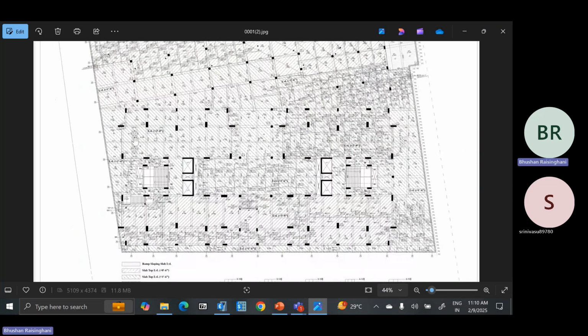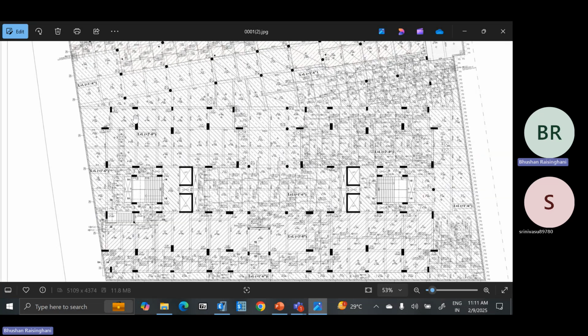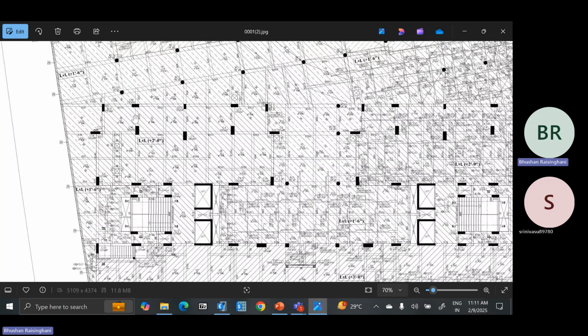So the building is up to this particular limit. That way you will have to generate the model. Without the podium, that is the first thing you will generate; if you want to make the arrangement more complex for analysis and design, you can add it later. So this is the building limit to model. Just for reference, I have shown it to you.